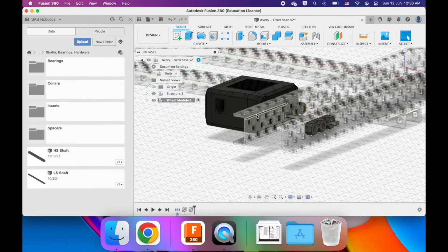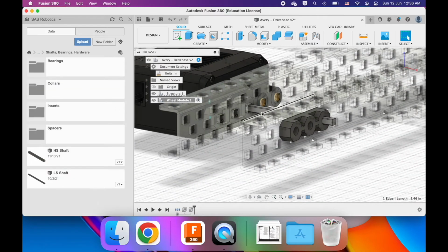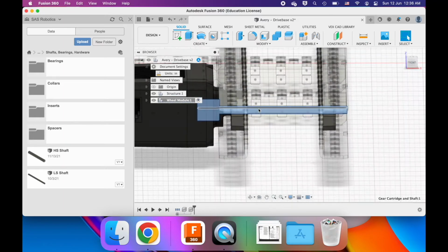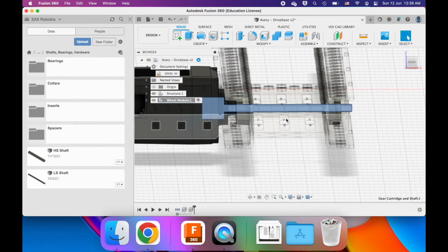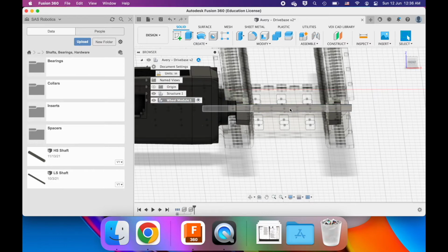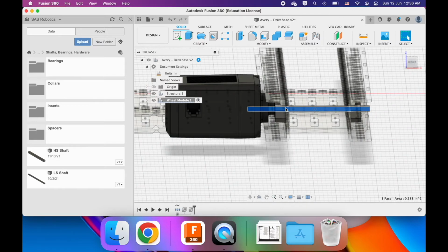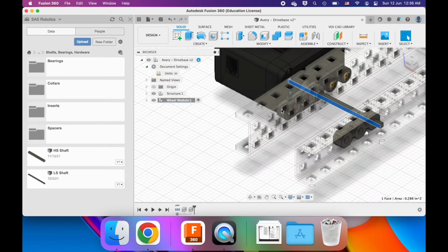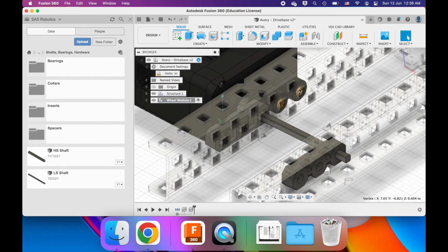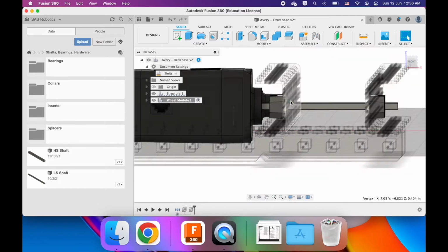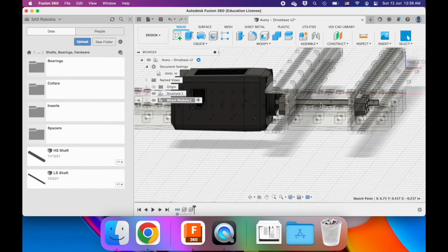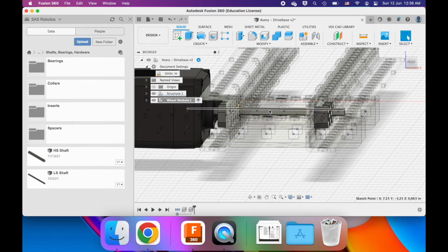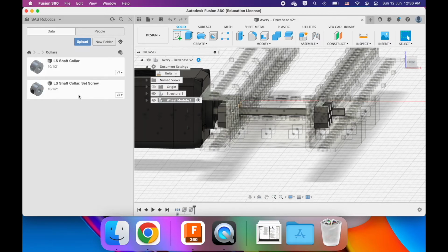Okay, so something else to keep in mind is this axle, in real life, can slide around left and right. Okay? And what does this mean? Right now, if you tried pushing it left, it would just hit into the motor, okay? And the motor wouldn't fall out because we'd have 2 screws here holding the motor in place, right? So that's fine. But let's say your motor tries to shift to the right, okay? It would then be able to simply fall out, okay? And that's a problem for us.